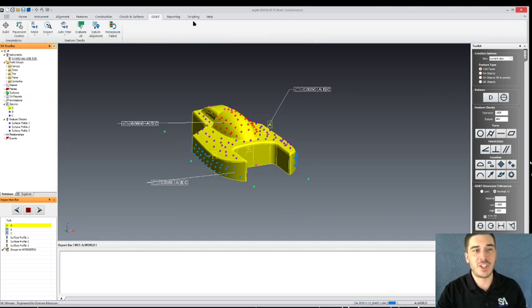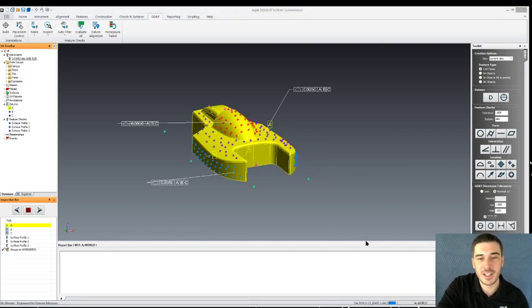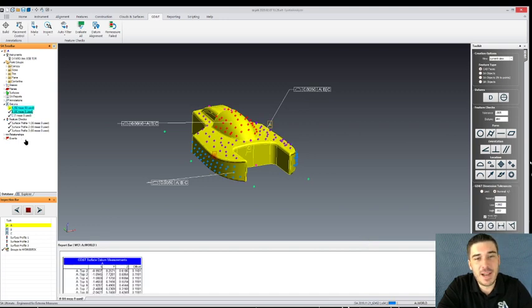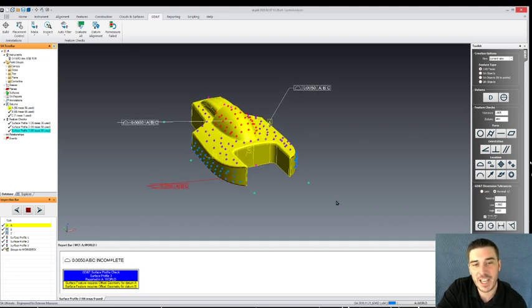So if I go back to the GD&T and I select Auto Filter, just like we did before, filter all checks, select individual points, select point groups, and select point clouds. We don't have any clouds in there. Hit OK. And now we've got some measured data in here. Our feature checks, you can see, is showing 36 measurements, 56, and 66. But you'll see that it's giving us an error here, and it's showing that in order to evaluate these surface profiles, it needs offset geometry for datums A and B.